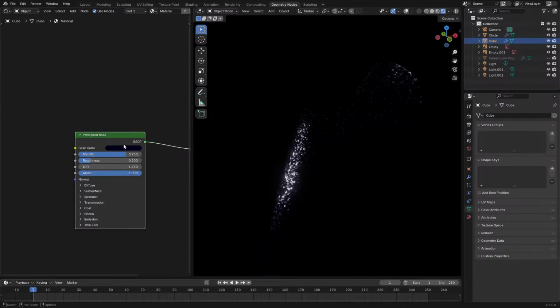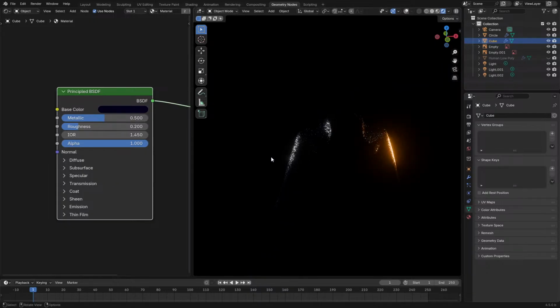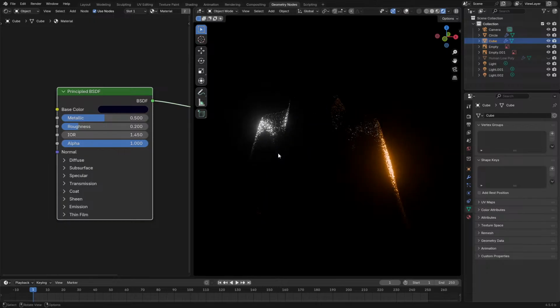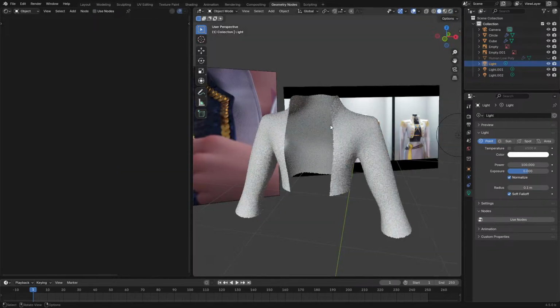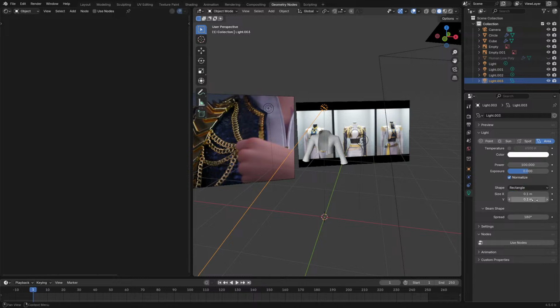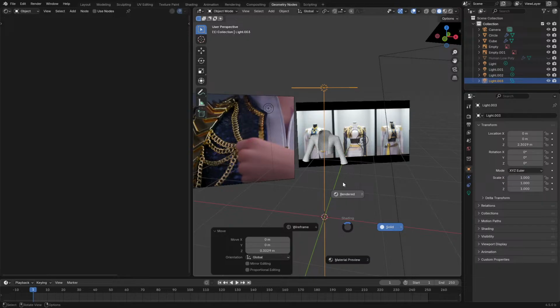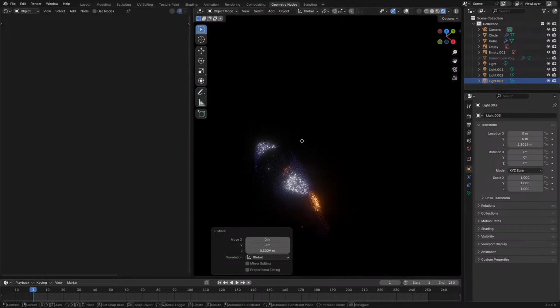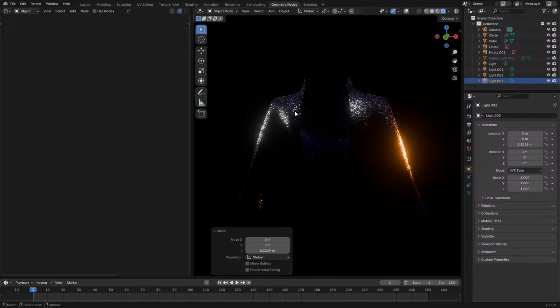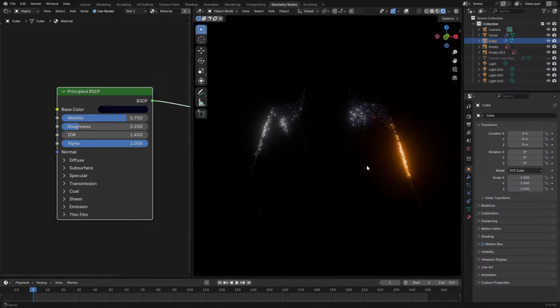So another thing is I could try putting in subsurface scattering. Wow. Okay. Yeah, let's set up some better lighting. We have that. And I'll need to set up a... Let's set this to be like 1 and like that. Let's go and reset the angle. A nice overhead light. Okay, no, it needs to be more metallic, because the less metallic we go, the worse it looks. So let's set that to 0.75.